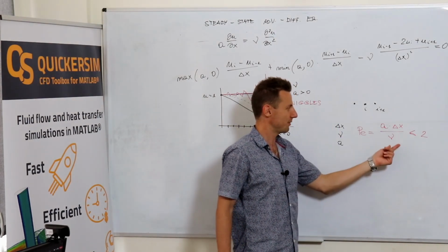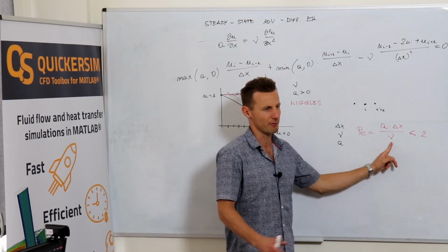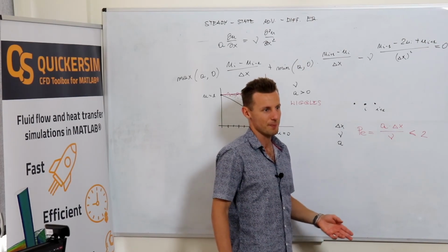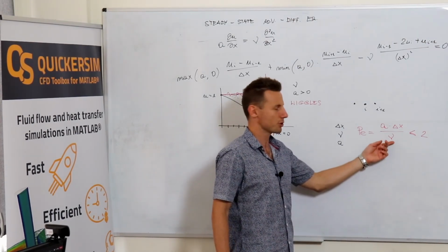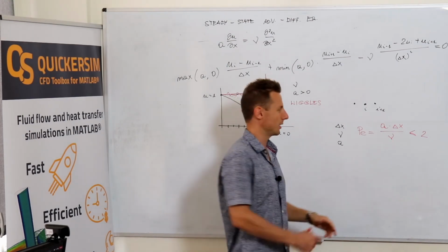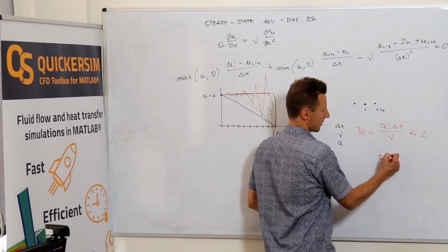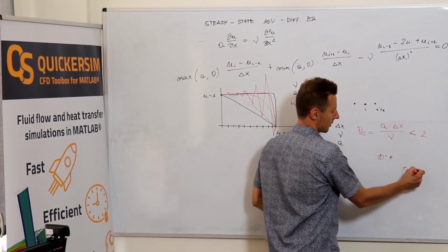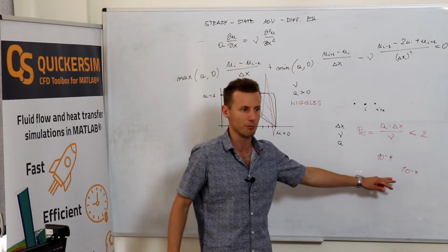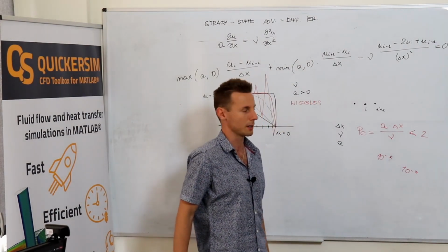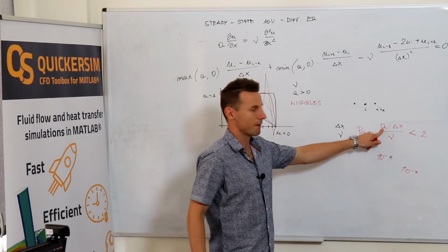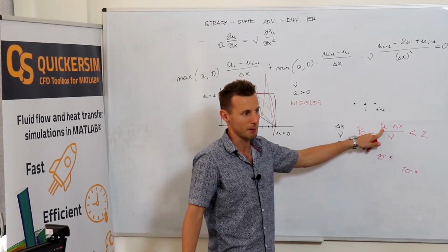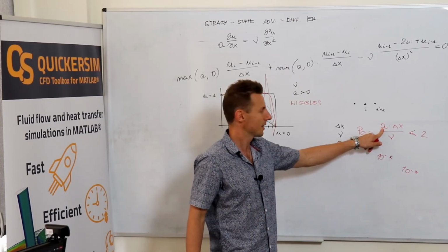Usually in physics, the diffusivities, whatever phenomenon you've got, like thermal conduction of fluids, viscosity, mass diffusivity, are usually maybe 10 to the power of minus 2, maybe for heat conductivities, probably something like 10 to the power of minus 5 or 10 to the power of minus 6 for kinematic viscosities, with velocities that you can have in engineering applications like 10, maybe even 100 meters per second.